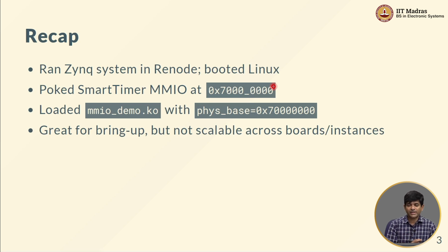Not just that I cannot expect it to do that, if a system ever tries to do that, it is going to be very dangerous, because the only way I can detect a particular thing is by trying to read from an address. And as you have seen, depending on how hardware is constructed, even just reading from an address might be enough to modify something inside the system. For example, we have already seen how we can write a register or a flag which clears on read. Just the act of reading from the register is enough to change the flag setting to 0.